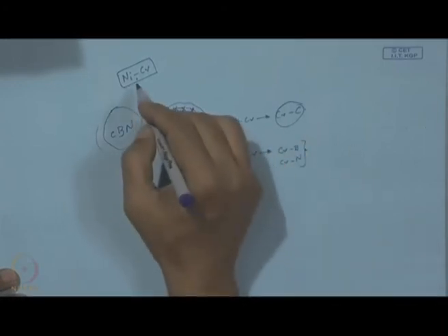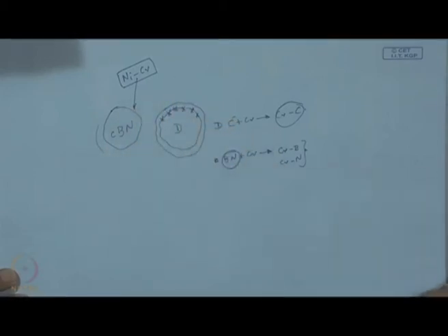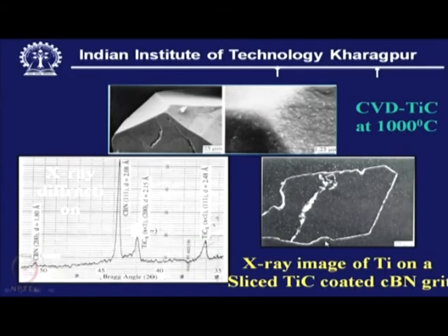So, what is done here to make it wettable? An attempt was made, and it was made with success. In this case this TiC was deposited using the well established CVD technology, and this is the coating on this CBN grain, which is actually a monocrystalline, very strong grain. It is seen that at the intersection of these two crystallographic planes on this side, these are well covered, and the edge is also a very sharp edge, where we also have very good coverage of the coating.